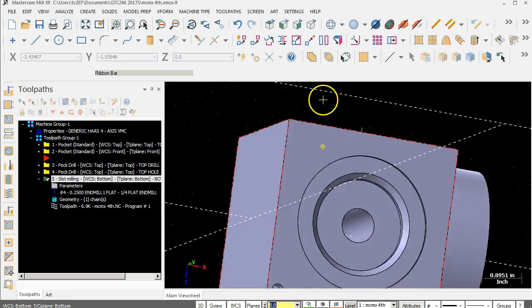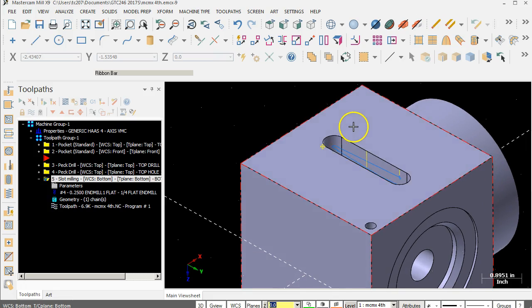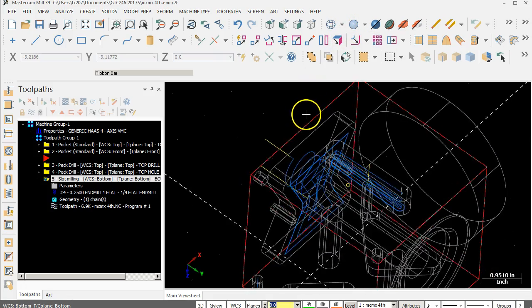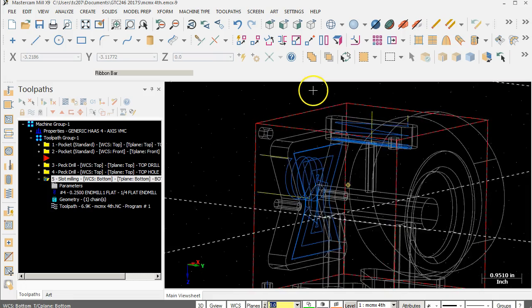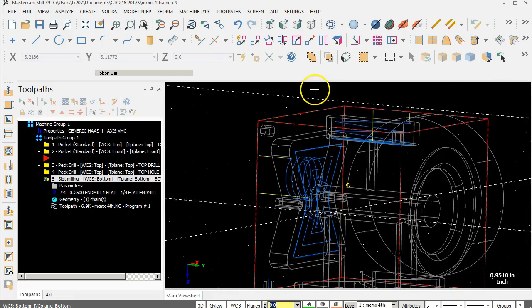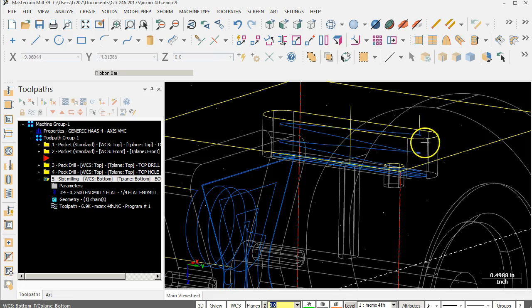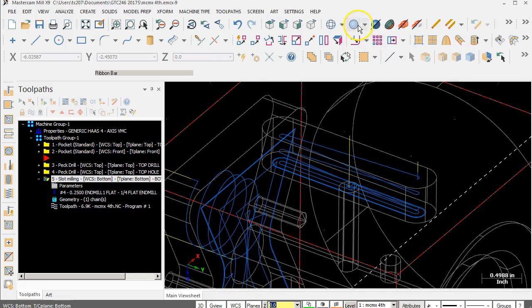All right. So what I'm looking for, and this is where we need to have the surfaces on. So let's switch it over to wireframe. And you can see how this is going to get kind of complicated if we stayed just with the IGES file. But the biggest part of this is looking through all of those lines and arcs and circles and being able to decipher what's going on. It's a lot of information. Anything you can do to make it simpler is going to help you out. All right, so it's taking the ramp in, does the finish passes, that's the desired result.